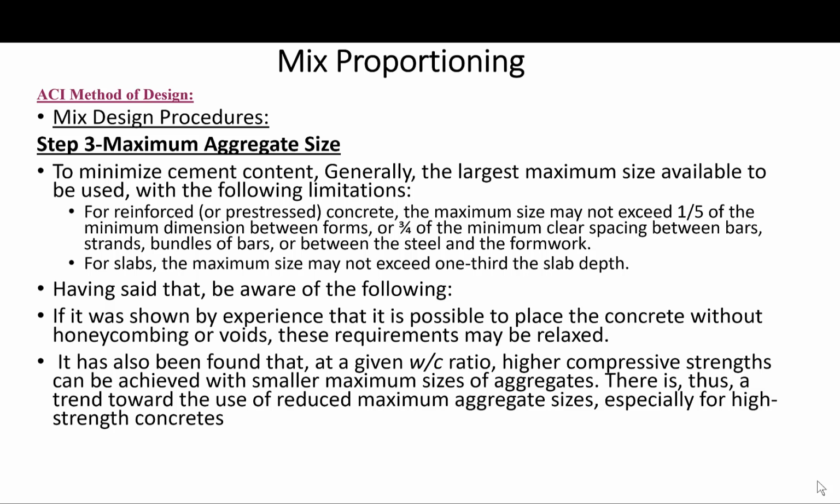Also, in many areas, the largest sizes available are between the 19 or 25 millimeter, the 3/4 inch or 1 inch. It should also be remembered that for a given job, it may be unwise to recommend different maximum aggregate sizes for different parts of the structure, as this may lead to confusion and increases the probability of error.